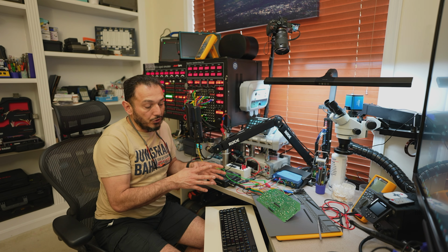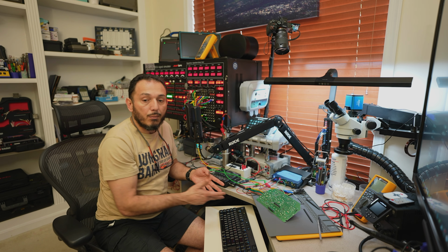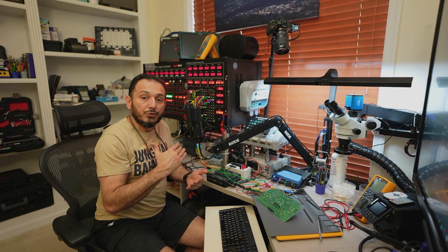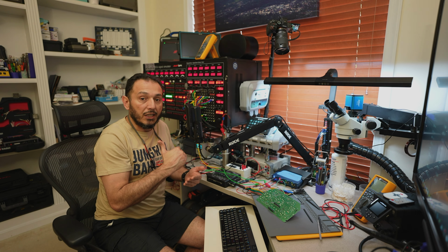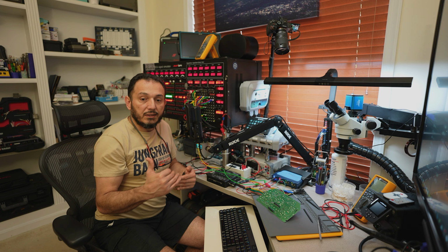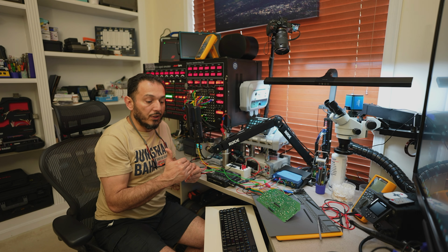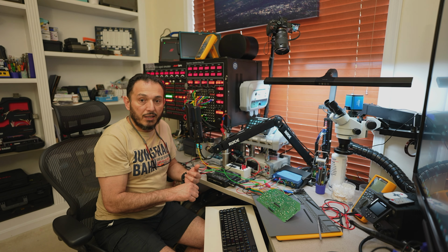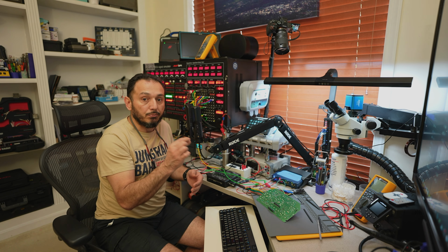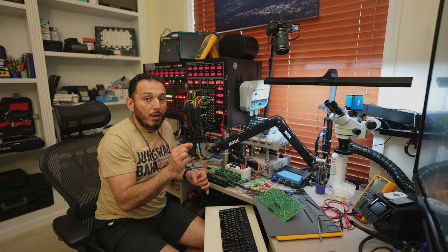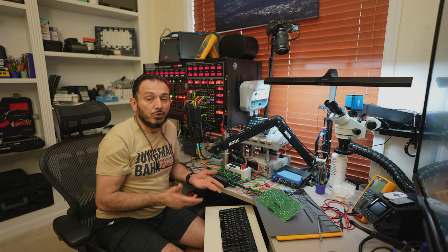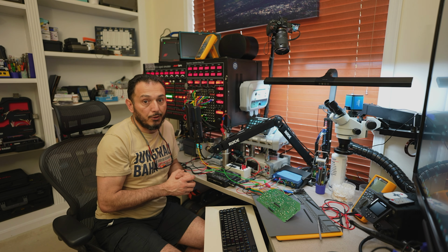Also, because you see the cluster is completely apart, I'm going to show you how, after you put it together, to reset the needles to the correct position, not just 0. With the scanner, we will have specific points like the tachometer at 1000 RPMs, the speedometer at 40 miles an hour, and the fuel level at 50%. That will give me a gauge to make sure the needles are set properly, and for you to make sure your cluster is going to be reading accurately. And that's very important, right?